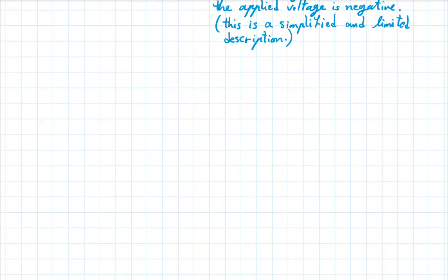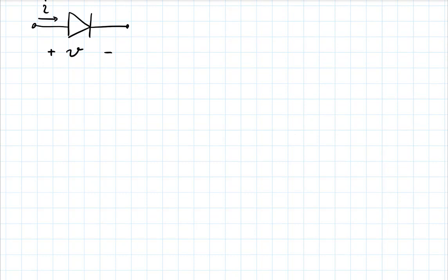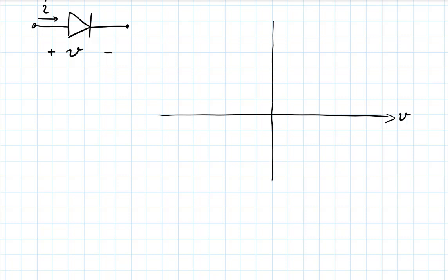Okay, so as I just said, the schematic of the diode is like this. And like any other element that we work with, we have to assign a polarity to the voltage and current. And conventionally, this is the voltage polarity that we assign. And this is the current direction that we assign. Again, you could, of course, choose other polarities, but then you have to remember that those are the negatives of this. And so it's better to go with this convention to avoid confusion. And this is what the IV characteristics actually look like in greater detail. So this would be V, and this would be I.